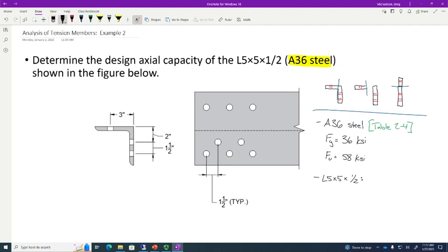Question, yes, sir. Would there be an example of a situation where 80 KSI would be used? So I can think of two really good examples. First off, for beams in buildings, probably not, except for if they're in their lateral system for earthquakes. So when would a grade of steel be that useful in building design? A good example would be columns in really tall buildings, okay?